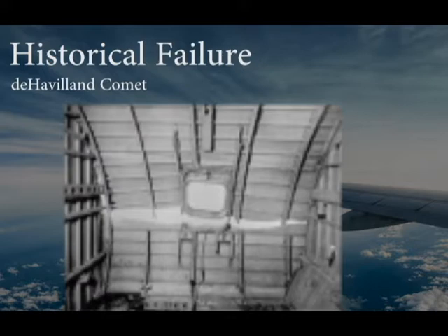Because of the de Havilland Comet's failures, manufacturers learned how important window design is when designing new aircraft. Due to this, all manufacturers began incorporating rounded windows to reduce the stress concentrations, and thereby increasing the life of the aircraft.